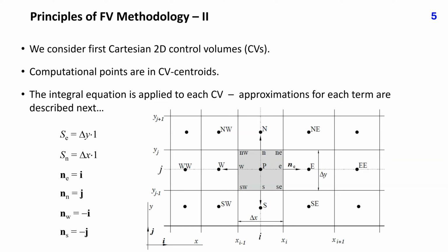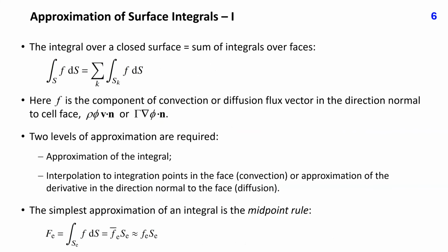The integral equation is applied to each control volume. How the individual terms are approximated is shown in the following slides. The integral over the closed control volume surface is equal to the sum of integrals over its faces. For the sake of simplicity, we shall first consider an arbitrary function f and see how it can be numerically integrated over the face Sk.